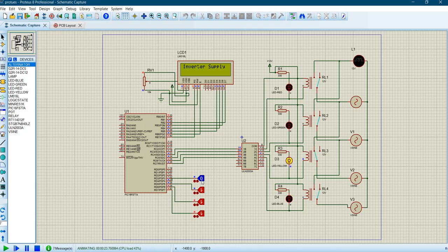If all sources are available, the first preference is going to be the main power supply, and when it is not available, solar, and when that is not available for the supply purpose, then switching to the inverter power supply. And when it is not available for the source to the load, the generator power supply is used. So when no power supply is available, directly no load is enabled, and all the relays are in off state only. Okay, so these are the power sources we are providing to these loads through this relay. Right. Thank you.